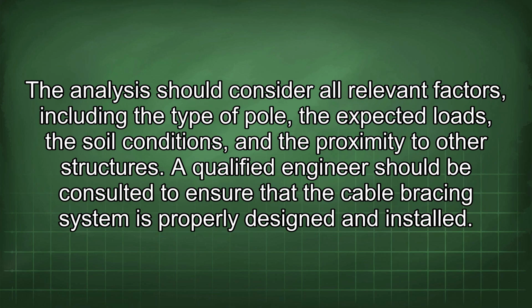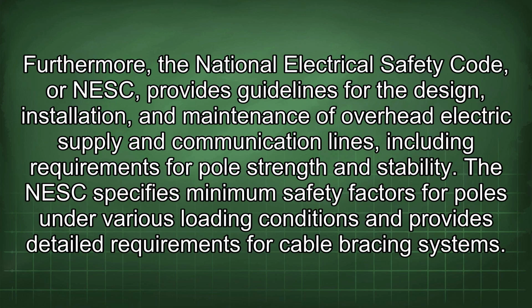The analysis should consider all relevant factors, including the type of pole, the expected loads, the soil conditions, and the proximity to other structures. A qualified engineer should be consulted to ensure that the cable bracing system is properly designed and installed. Furthermore, the National Electrical Safety Code, or NESC, provides guidelines for the design, installation, and maintenance of overhead electric supply and communication lines, including requirements for pole strength and stability.